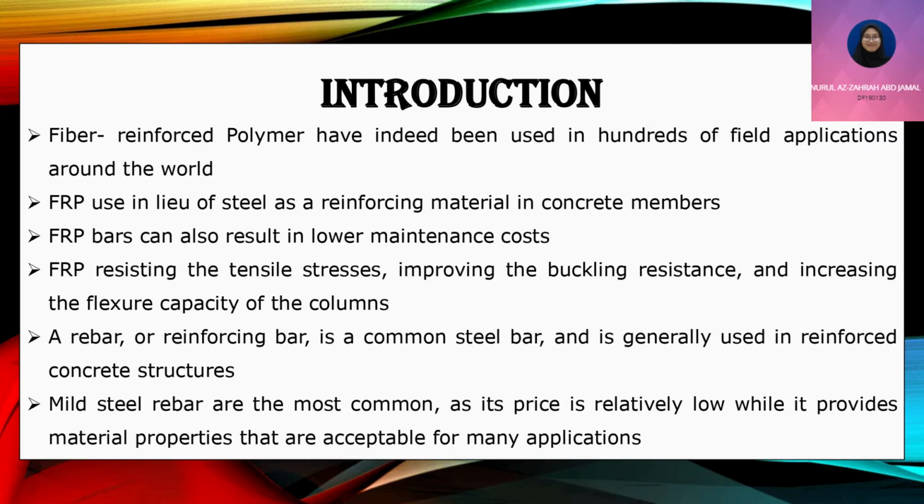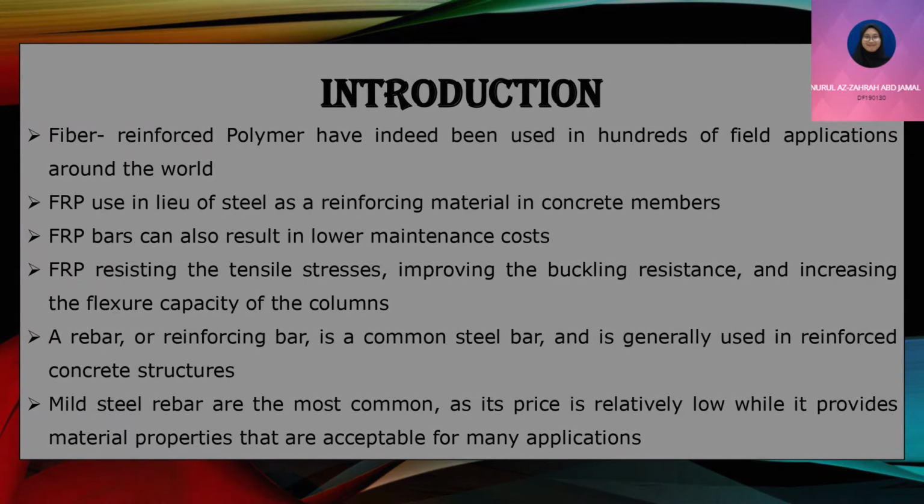Longitudinal internal reinforcement plays an important role in resisting the tensile stresses, improving the buckling resistance, and increasing the fracture capacity of the column. Besides, a rebar or reinforcing bar is a common steel bar and is generally used in reinforced concrete structures. Mild steel rebars are the most common as its price is relatively low while it provides material properties that are acceptable for many applications.